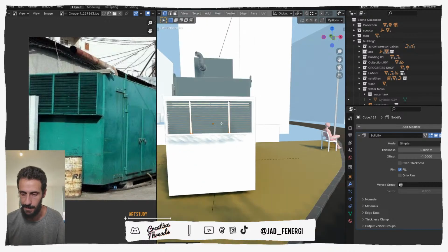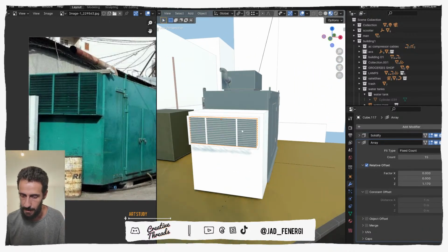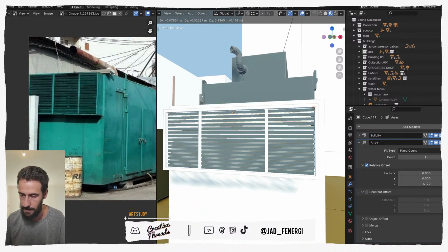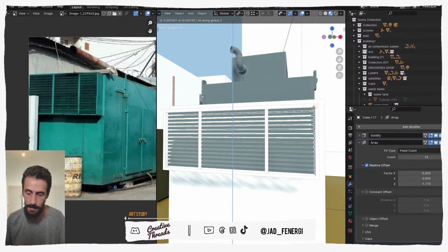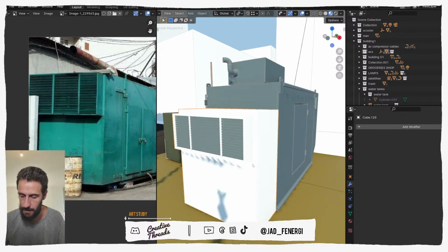I learned this probably yesterday. It's something amazing. Let's say you want to move this, you press B, it snaps back to its place, and you say you want to align this, but just on the Z axis to this, so they're now snapped together. It's really helpful actually.